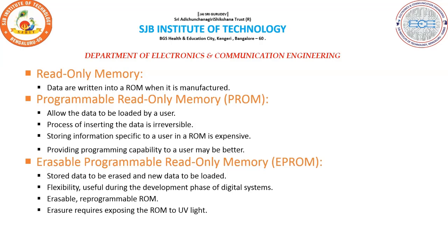Programmability is achieved by inserting a fuse. Earlier, in the figure I showed in the earlier video, instead of the transistor P they are going to implement the fuse. Before it is programmed, the memory contains all zeros. The user can insert ones at the required locations by burning out the fuses at those locations using high current pulses. So the PROM provides flexibility and convenience not available with the ROM.